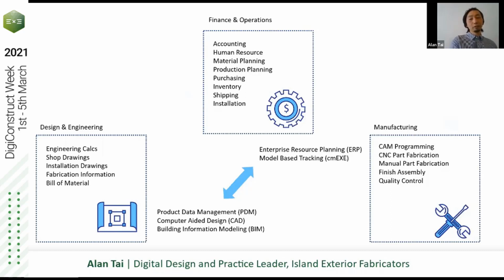And we're using different types of CAD software and BIM tools, including AutoCAD, which is more for 2D detail development, and move into a Revit model to create a representation around LOD 350 that we can generate shop drawings from, and then move into the fabrication using Rhino Grasshopper or Inventor for fabrication modeling. And these data will be saved into PDM, a product data management system.